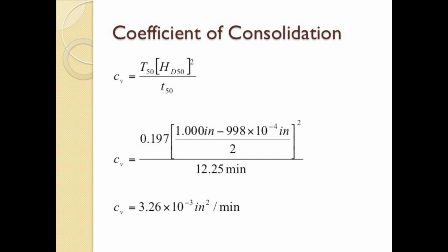This result aligns with Casagrande's result. This makes sense because the two time deformation plots were constructed from the same pressure increment. Not only are the results on the same order of magnitude, but they are within 13% of one another. This ensures our methodology is correct.